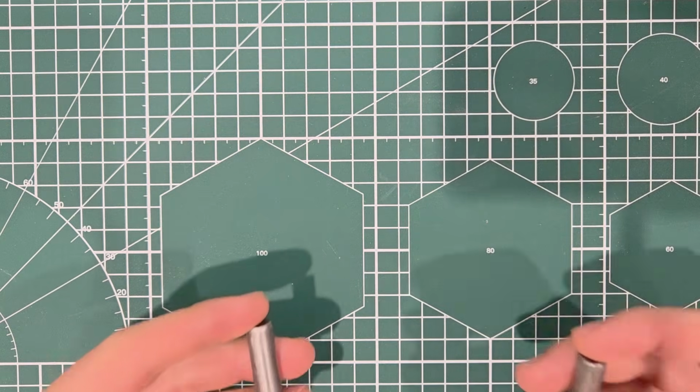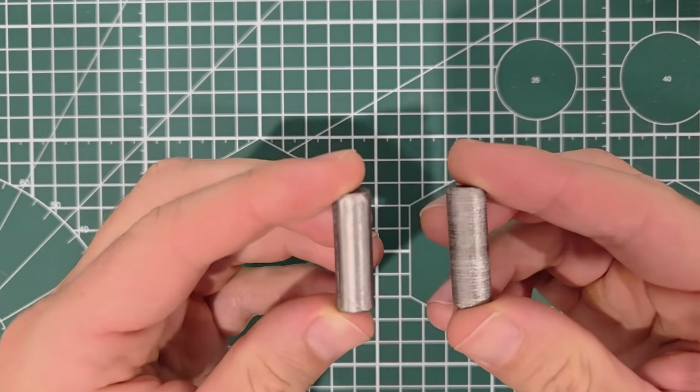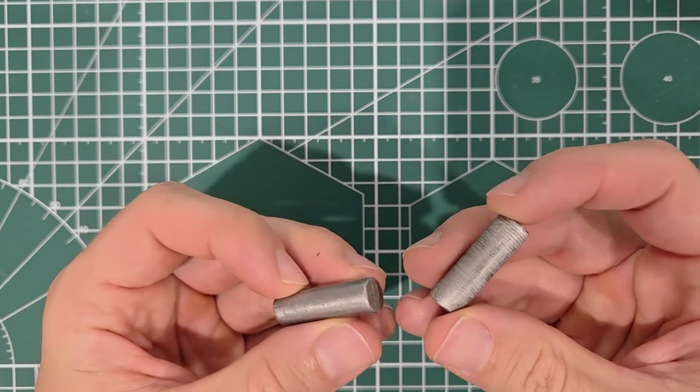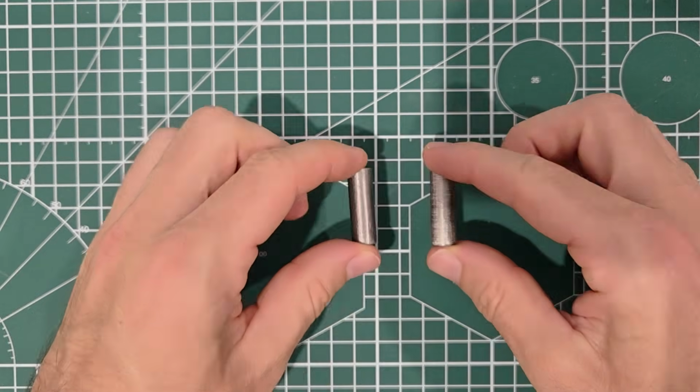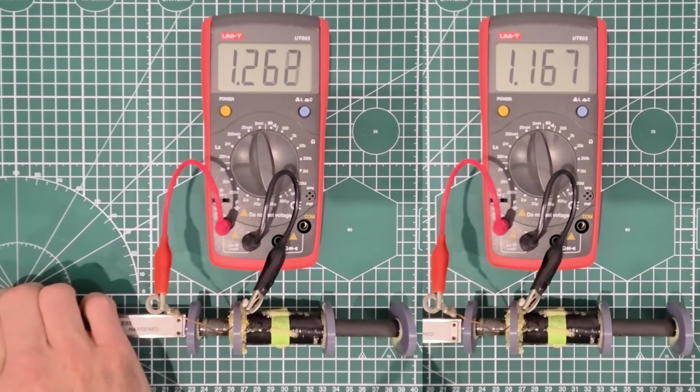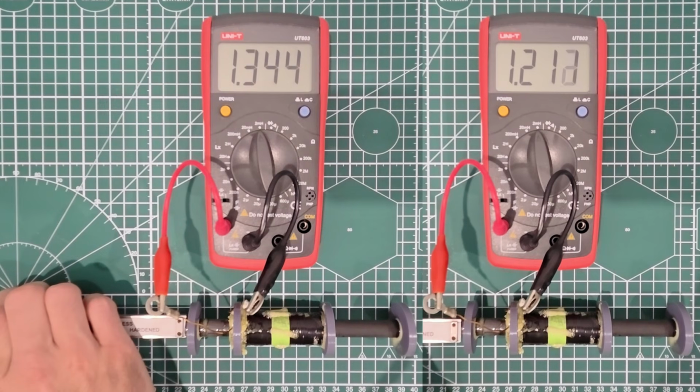So to test this, we will compare a mild steel projectile, which has a permeability of about 2000, with a soft iron projectile that has a permeability of about 5000. When measuring the inductance, we can see it is higher with the soft iron projectile in the center of the coil, meaning there will be a decrease in the rate the current ramps, but will the gain from the higher permeability projectile be able to offset this?